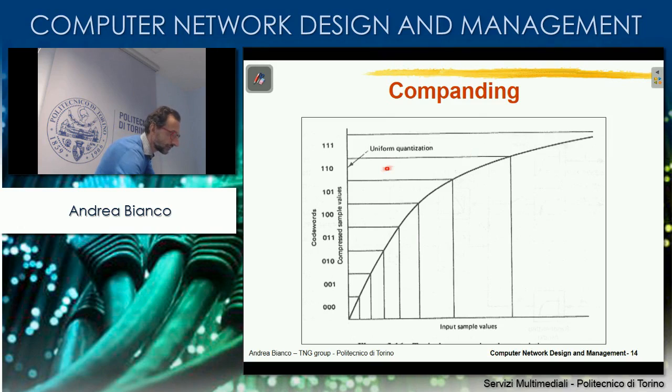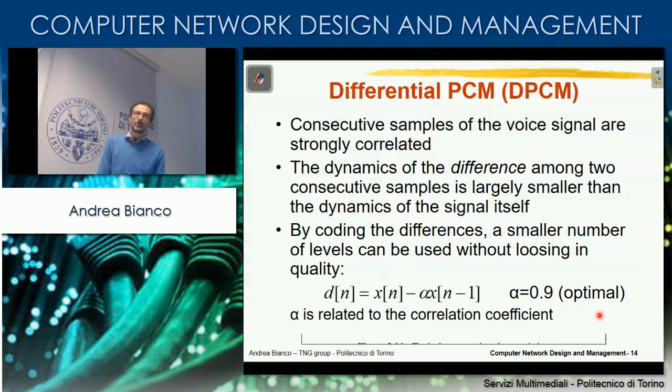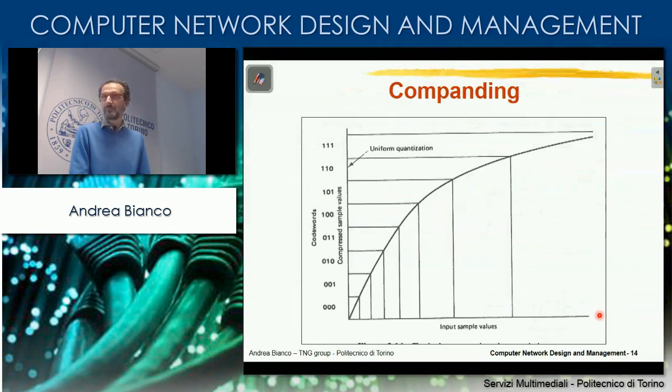You see that if you compare this uniform quantization with this step, here the quantization error is huge. Okay, but who cares? We are very rarely going to use it. Signals in that area are very, very rare, and so at the end we get a better quality with a smaller number of bits. That's also called companding. Okay, that's the most popular PCM scheme.